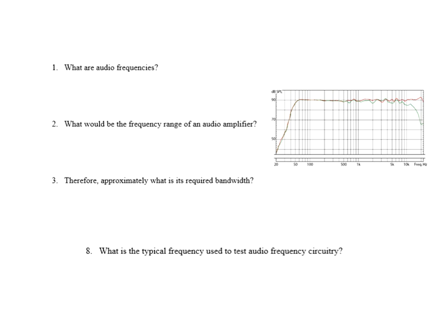Well, what is the audio frequency range? Well, the audio frequency range is between 20 hertz up through 20 kilohertz. Those are the range of audio frequencies. What is the bandwidth? Well, the bandwidth is the upper frequency minus the lower frequency. In this case, 20 hertz is so much lower than 20 kilohertz, it's almost zero. You can say that the bandwidth that you subtracted is approximately 20 kilohertz.